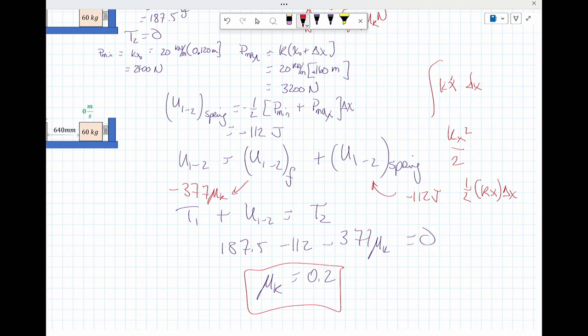So it's always the same definition, work equals force times delta x, or force dx, really. And from that, I will end up with 1/2 kx squared. I have to make sure that I'm in the right direction. It's opposing motion, and that's where I get the half. Go ahead.